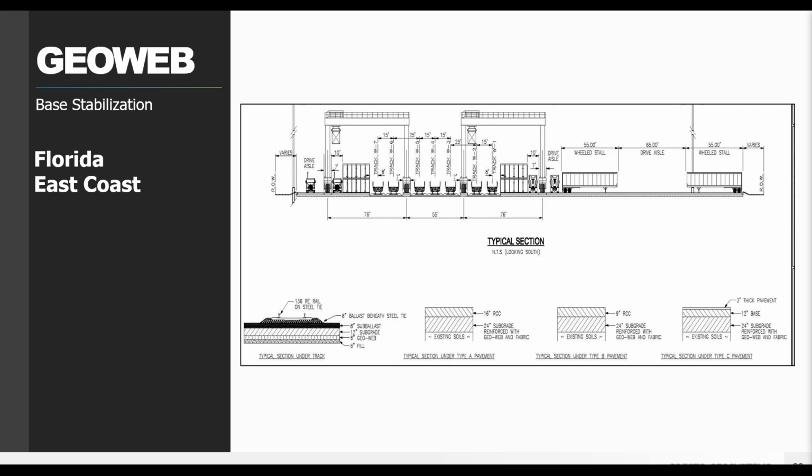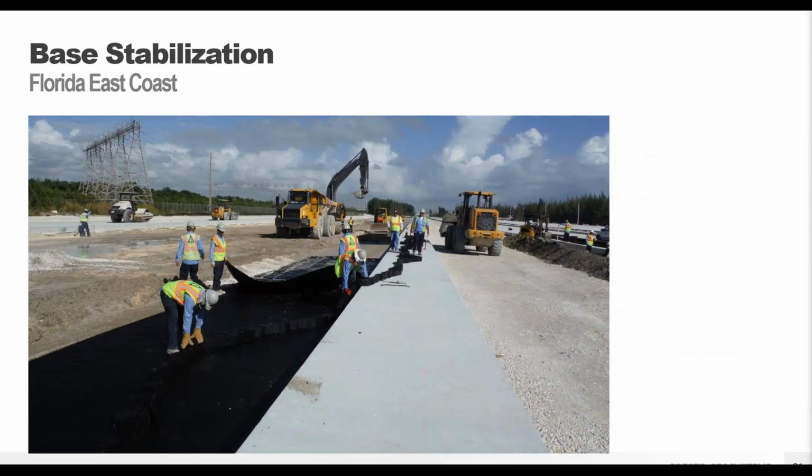So it's altering that stress bulb that we looked at way back at the beginning. This reduces the overall magnitude of settlement, but also protects against the damaging effects of differential settlement, allowing for primary consolidation of subgrade materials to occur in a much more uniform and controlled manner. So the end result is a much more durable system with a longer pavement life.